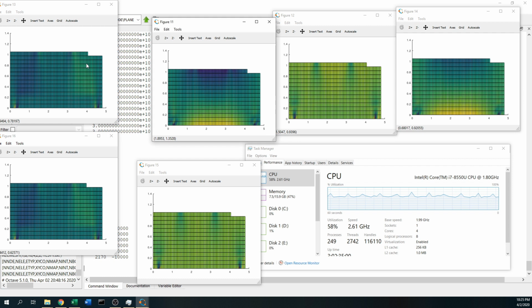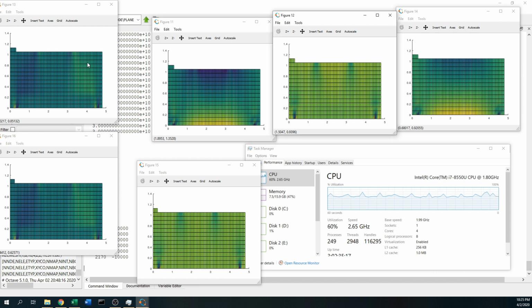You just get these components, sigma x, sigma y, tau xy and put all of these into the Mohr's circle formula you have learned in strength of materials, and then you can find the plane corresponding to the max principal or minimum principal, max compressive, max tensile. It can all be done, but I don't have time to do every single thing for you.